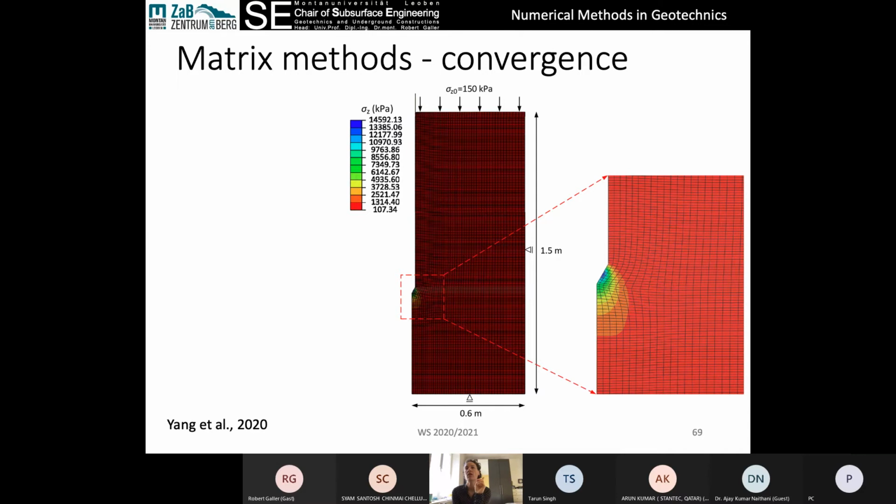And if the mathematics are so complex, maybe the material is so weak, whatever it is about the setup, that it cannot converge, it cannot come to a solution where the forces are more or less balanced, then the code will return a failure. It will say, I have not been able to converge, the deformations are going too crazy, the stresses, I can't get them to even out, to slow down. So you'll get an error message. And the reason is that it's not able to balance the forces.